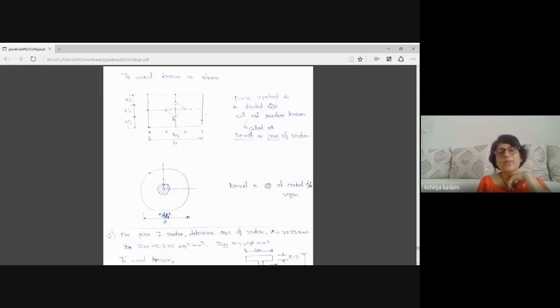So you can see in the sketch I have shown a dotted rhombus portion. This is the dotted rhombus portion which satisfies 1/3 for A and B directions. So in this rhombus portion, if force is applied, the entire column will be in compression. This shaded rhombus portion is called the core of the section or kernel of the section. It is the area of cross section where if we apply force, the entire column will remain in compression.